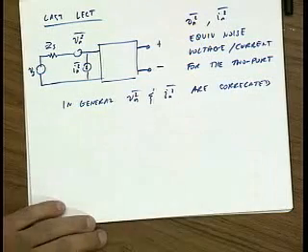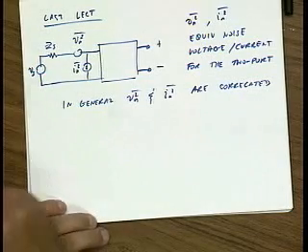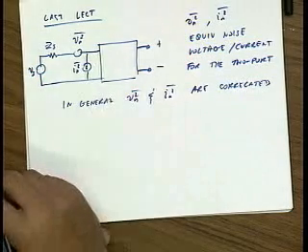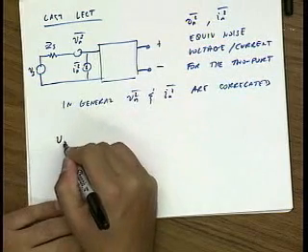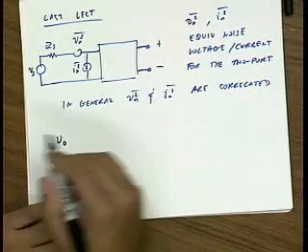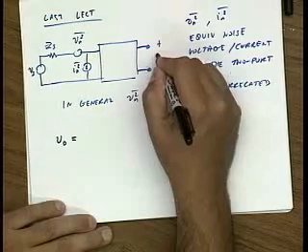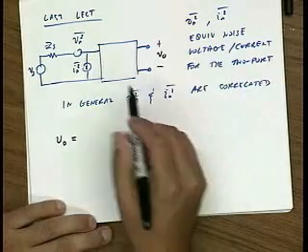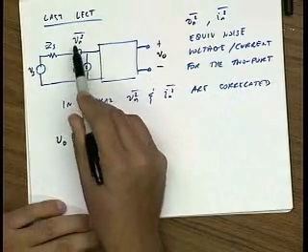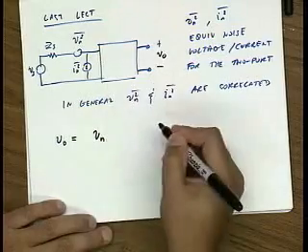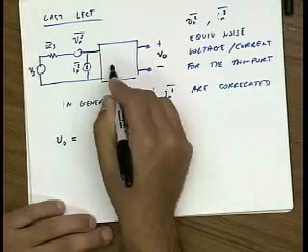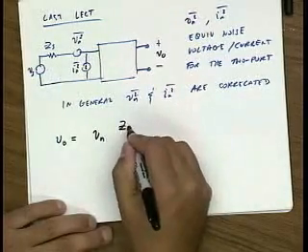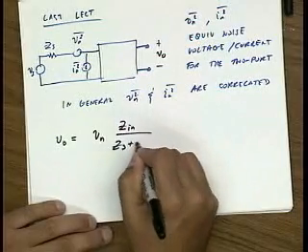For the moment, I'm going to pretend like these are just normal voltage and current sources. I could say, if they were normal current and voltage sources, I can calculate the output voltage, V out here. Let's find the gain for V in. V in sees a gain, basically Zn divided by Zs, a voltage divider.